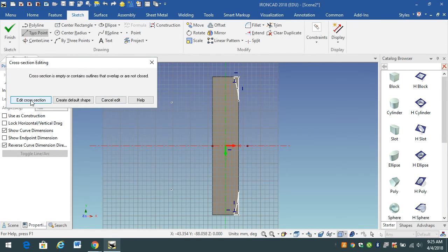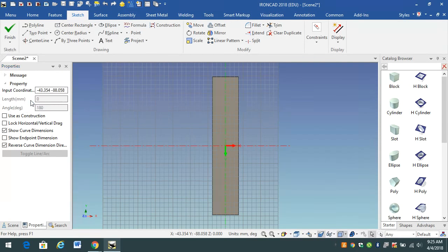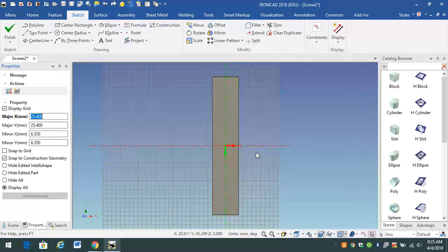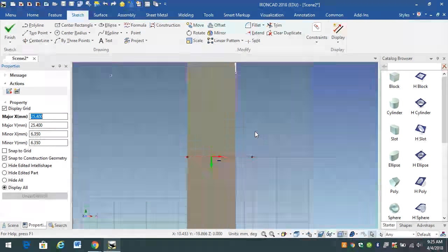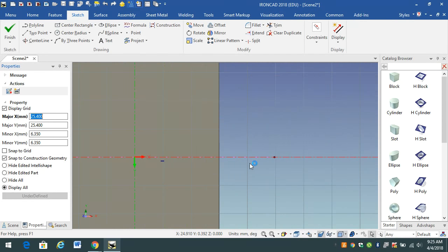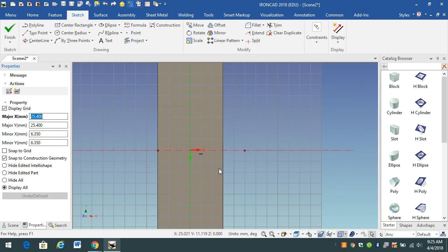And now I'm going to click back on my screen, and it's going to allow us to come in here and make some changes. So a couple of things that we need to do is we need to correct the issues. See this point here and this point here? These are lines, and I'm going to drag it off a little bit so you can see how that line is pink. A pink line after you have had an error indicates that, hey, this is likely where your error is coming from. So let's delete that line.